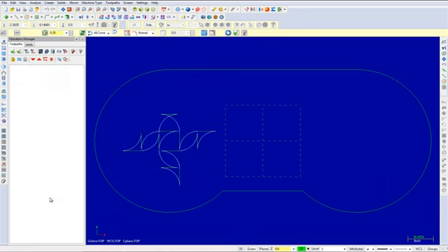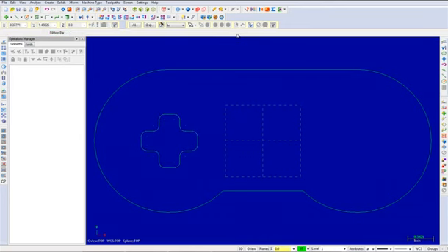Input the following radius value, 0.075, and press Enter. Your radius should appear as shown. You can now select the OK button to exit the Fillet Chain command. Your part will appear as shown up to this point.